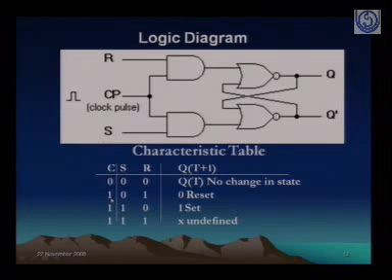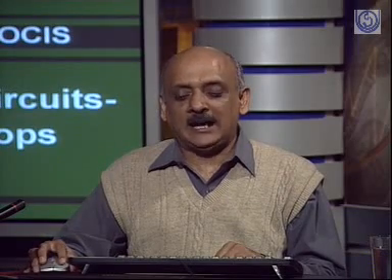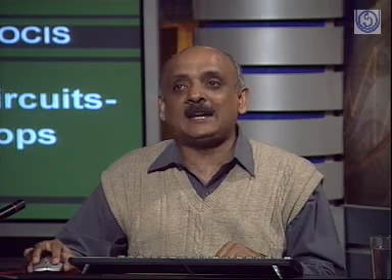However, now the first of these two represents the reset state. So what happens? A clock pulse occurs, the S value is 0 and the R value is 1. So on the occurrence of the clock pulse, the flip-flop goes to the reset state. That's what we saw in the latch. So it goes to the reset state, which means the value of Q becomes 0, and the value of Q dash becomes 1. You can try that out here and it should work out in exactly the similar way. And then we have the similar thing for the set state.